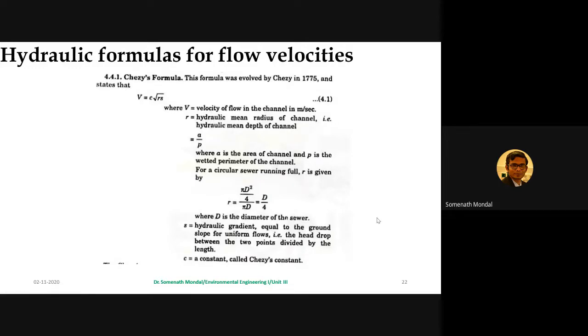There are sewers and stormwater drains, and we need to design them as open channels, except when it is specially required to design them as flowing under pressure, but that is very rare. In special situations like inverted siphons, and discharge lines from sewage pumping stations, which always flow under pressure, you have flow under pressure.